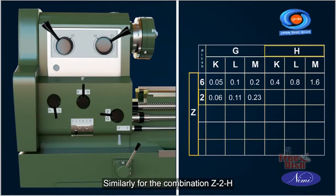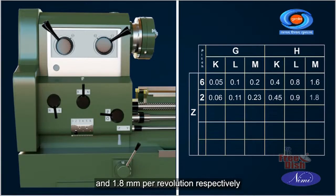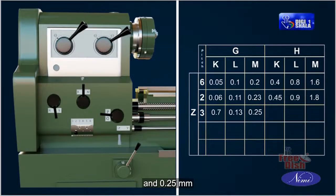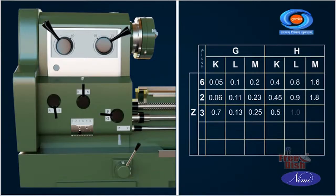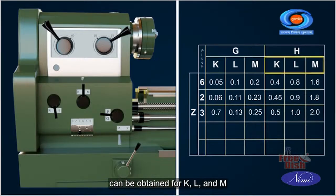Similarly, for the combination Z2H feed rates of 0.45, 0.9 and 1.8 mm per revolution respectively can be obtained for K, L and M. For the combination Z3G feed rates of 0.7, 0.13 and 0.25 mm per revolution respectively can be obtained for K, L and M. Similarly, for the combination Z3H feed rates of 0.5, 1.0 and 2.0 mm per revolution respectively can be obtained for K, L and M.